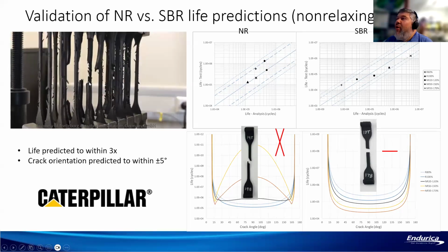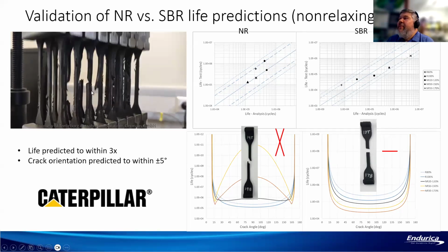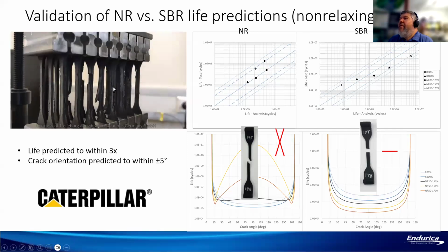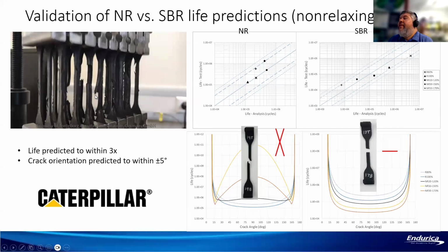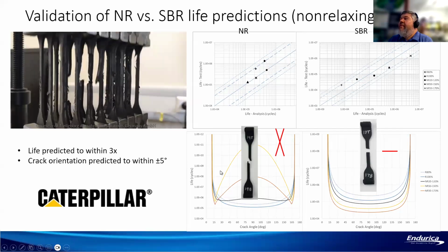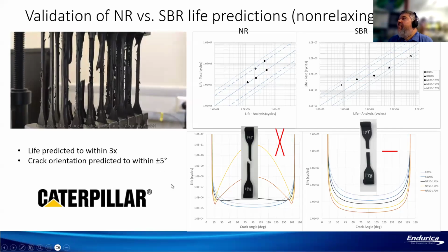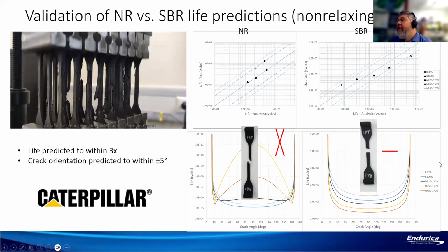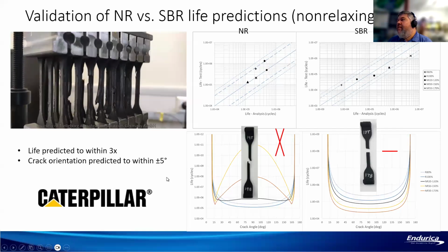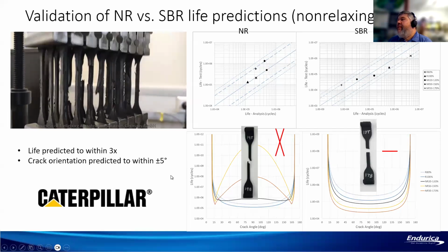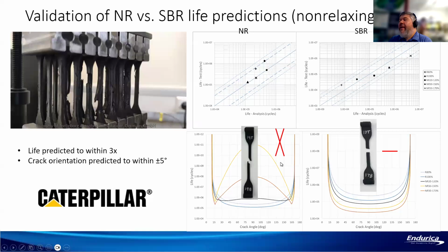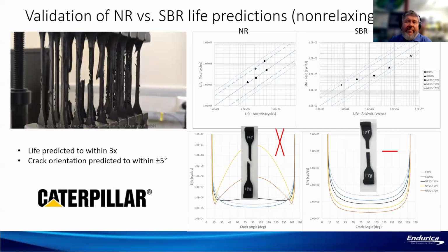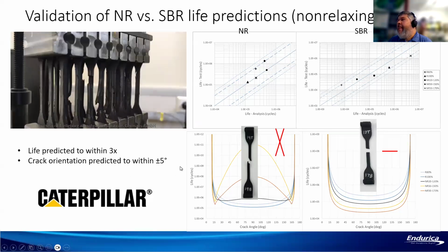If you look at the movie, you can see that the specimens are full of many cracks, and they're all at these funny angles that we can predict with our crystallization model. So that's an example of one way in which the code is highly accurate for rubbery material. A lot of times people look at this and say, oh, it's very mysterious behavior, and it's like, no, we've got models and we can predict that.